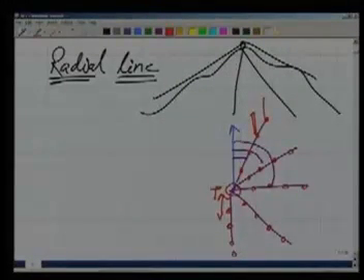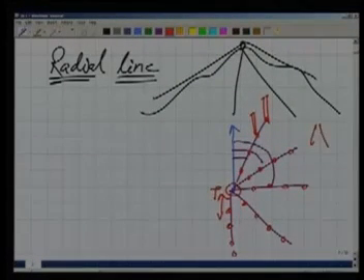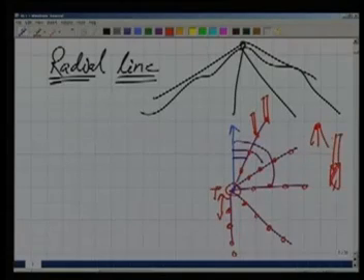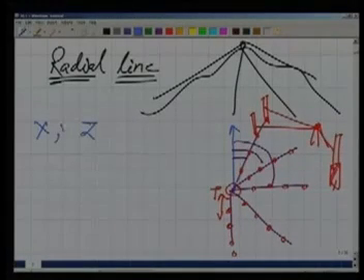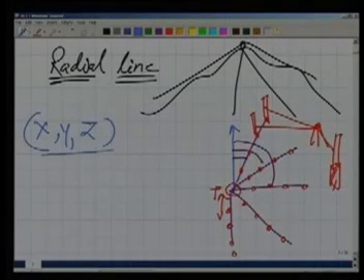The elevations can again be done by using the level, which starts from a benchmark where we are taking a backsight and then several intermediate sights. Again in this method, we are basically observing the z, but x and y are also being observed indirectly.